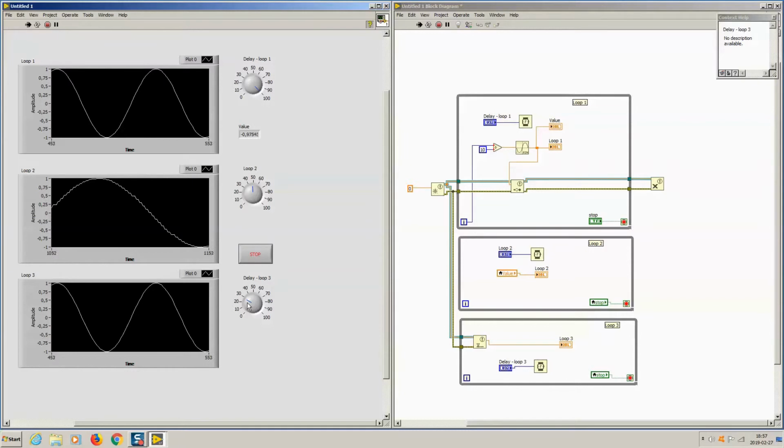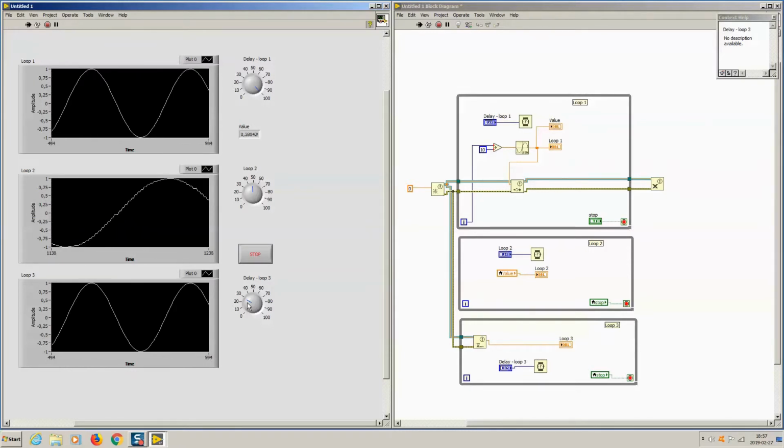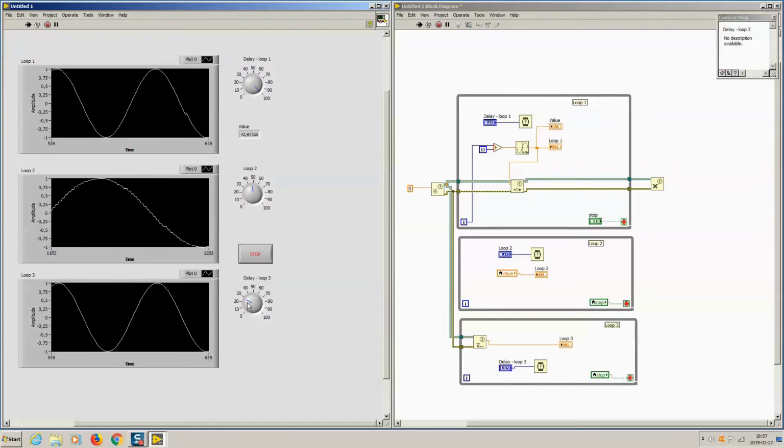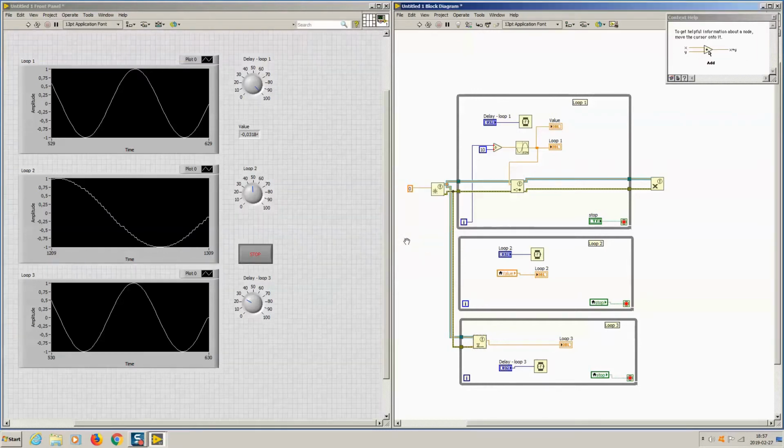The master-slave pattern does not need to be created from scratch, but you can use a ready template. To do this, select File, New, From Template, Frameworks, Design Patterns, Master-slave design pattern.